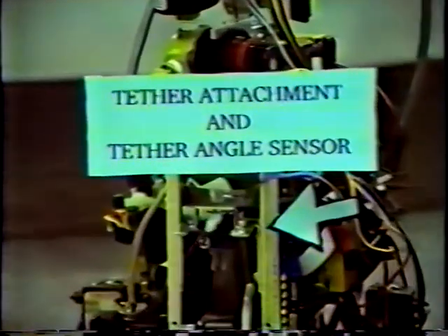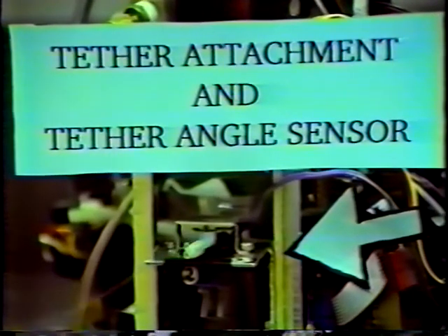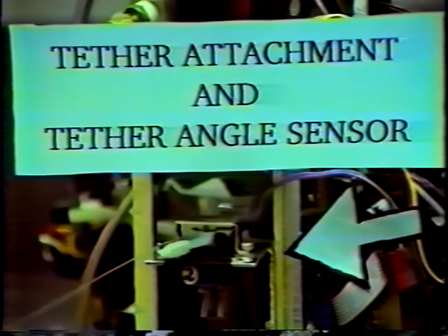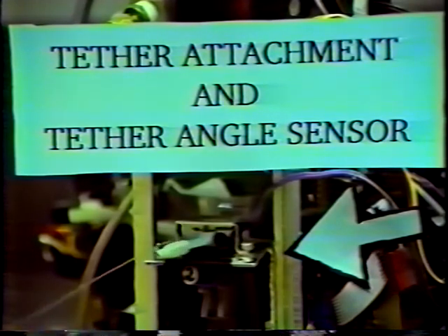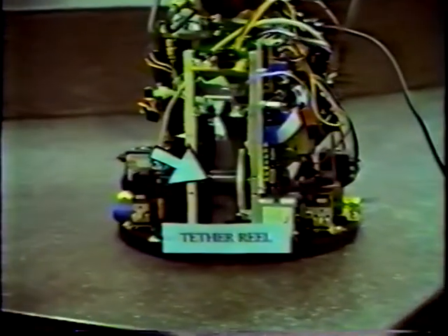That's a view of the control and data acquisition computer, and the signal conditioning electronics that are built on the front there. The computer runs off of a 9-volt battery. It's a low-power computer originally designed for data logging applications. This is one of the main sensors that I use, and the output of this was recorded on the plots that I showed. It measures the angle between a reference line on the module and the tether direction. It's a thin film plastic potentiometer.